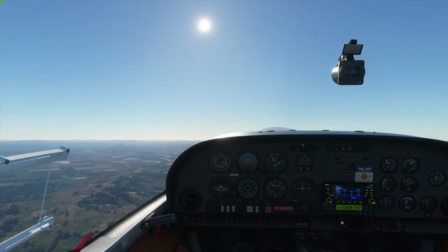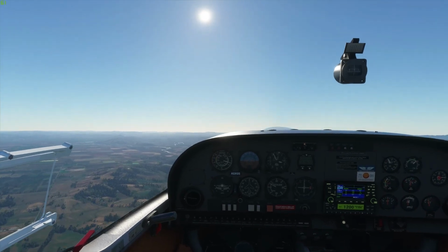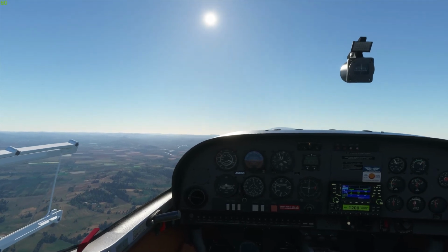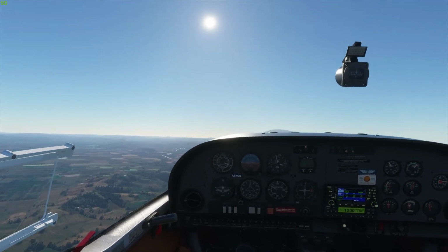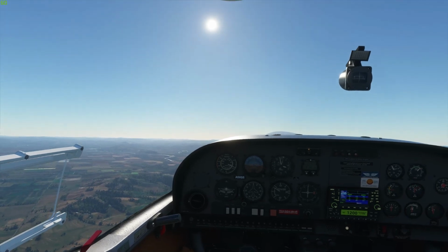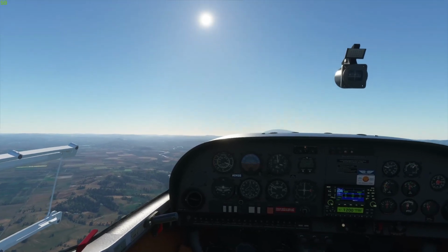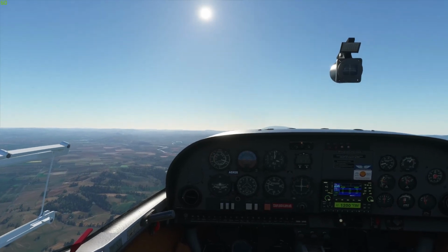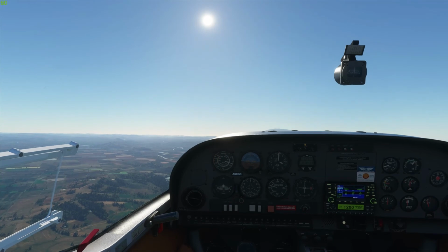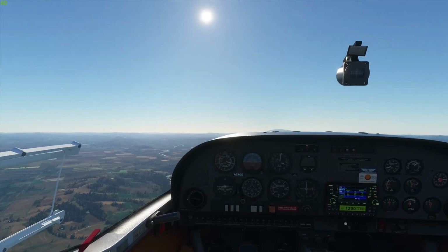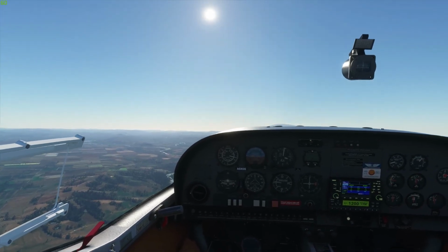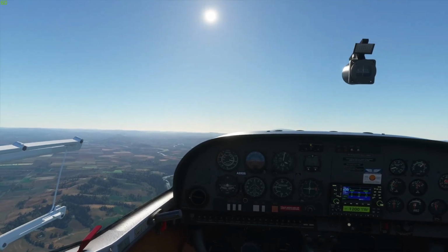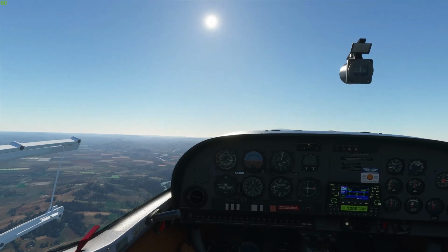And the next one we'll do a departure stall. So essentially we've got the flaps at the takeoff position, and this is a power on stall, so we'll do this. It really depends on the aeroplane, but I'll try 20 inches initially and just basically hold this attitude and see if it'll stall, but I think we'll have to go lower than that. We'll start with 15 and we should get more of a wing drop, but I really just held the stick back all the way through that stall warning, and I could have recovered at any time prior to that without too much issue. So it feels very stable.